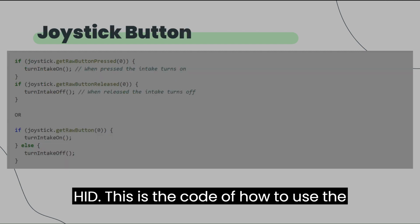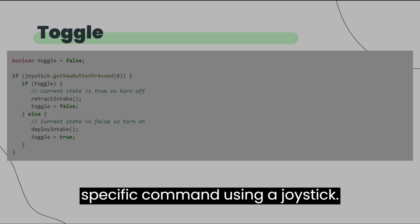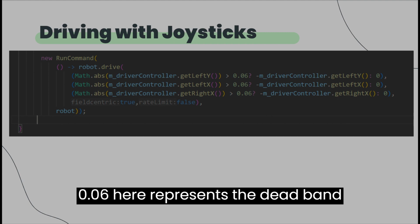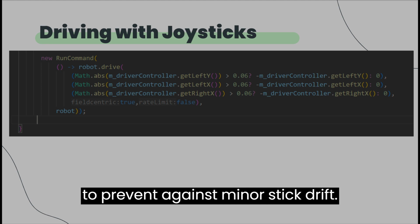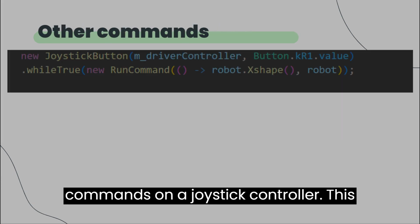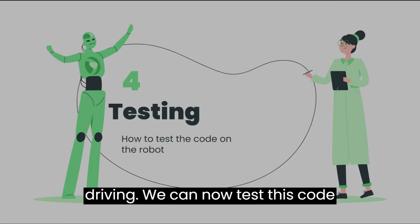This is the code of how to use the joystick buttons. This is how to toggle a specific command using a joystick. This is the code for driving with joysticks in a new command. The 0.06 here represents the deadband, to prevent against minor stick drift. This is the code of how to add any other commands on a joystick controller. This is how to use a joystick for anything but driving.